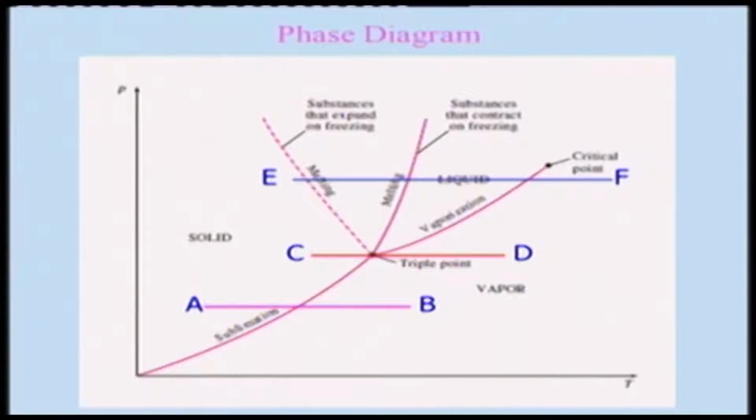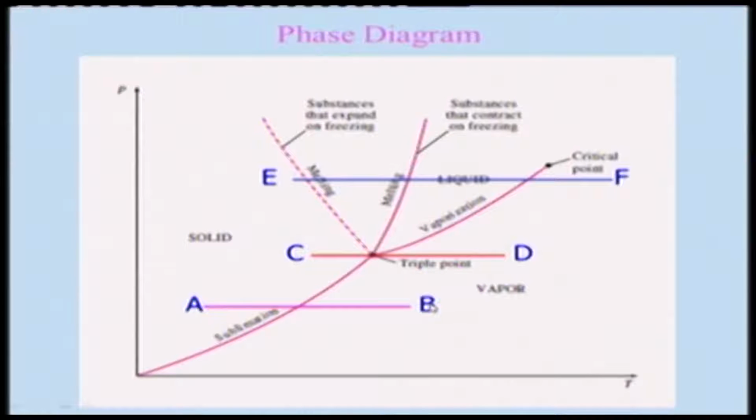Now, if you look at this phase diagram, it is a very compact one, but it will not give you a lot of other things. What are those? It is not depicting or describing. Can anybody tell me? If you look at this sublimation line, it is going directly from solid to vapor, but there is a situation where both the solid and the vapor will be existing, yes or no? That you cannot really describe in this. Similarly, for liquid to vapor, there will be wet mixtures, we cannot describe them in this diagram. And this diagram is very important, particularly for metallurgy and other things, and so also for steam or any other pure substances we will be dealing with.